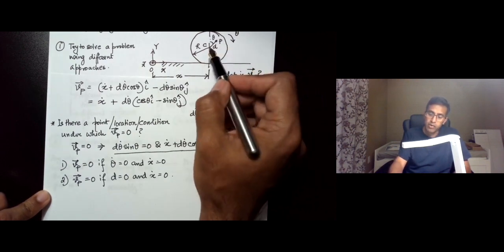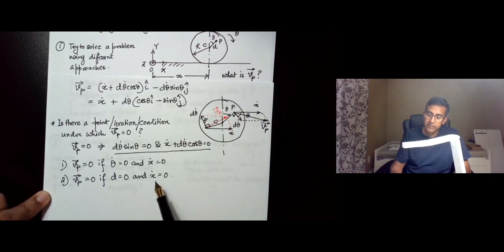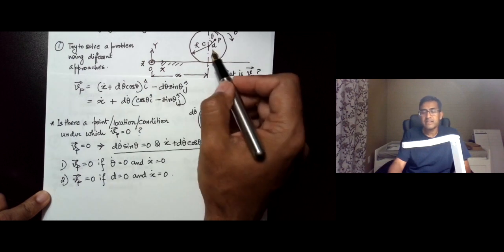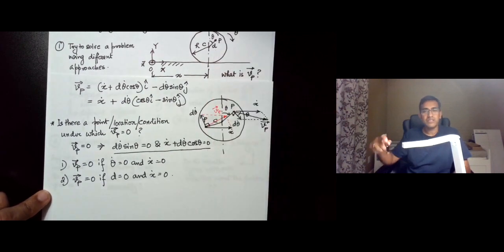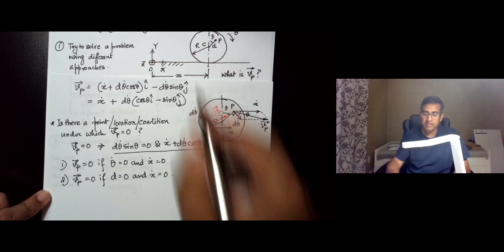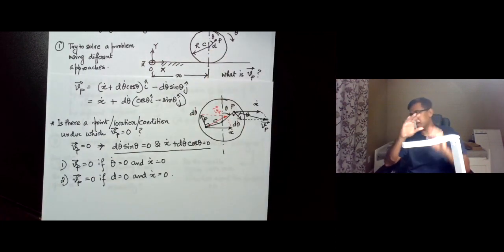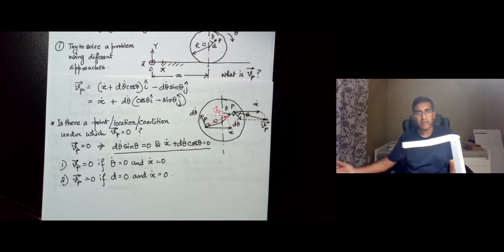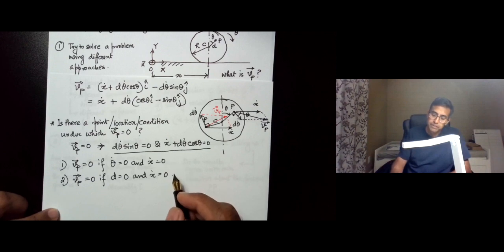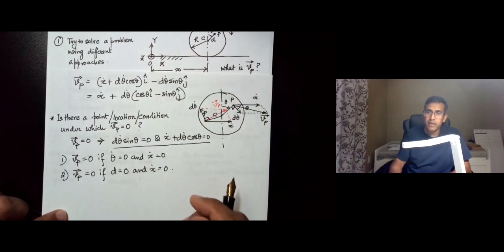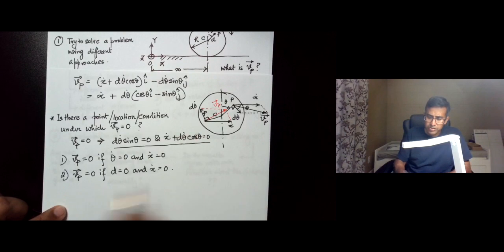So when you are at the center, and the disk is not translating, then C is not going to have any velocity, because just the spinning of the disk does not give a velocity to the point C, right? If the disk just spins but does not move, then the point C does not have any velocity. For the point C to have a velocity, you need the disk to have some horizontal motion in this problem. So that is also a relatively simple case.